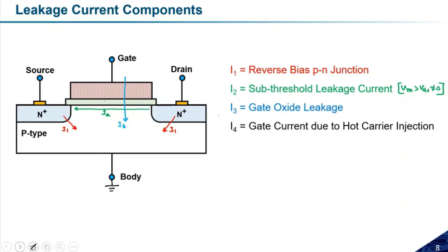With time, the electrons or the charge carriers get sufficient kinetic energy, and because we have reduced this oxide, and because of this reduction in the oxide and the high energy that the charged particles have gained, some of the charged particles can trap into the oxide region. If they are trapping into the oxide layer, there may be some leakage current flow.